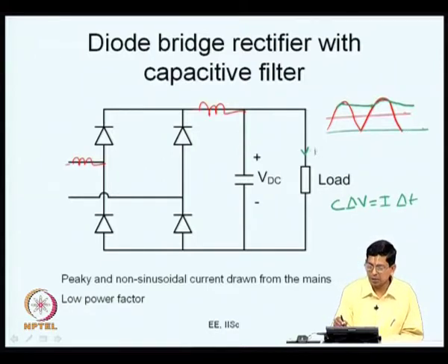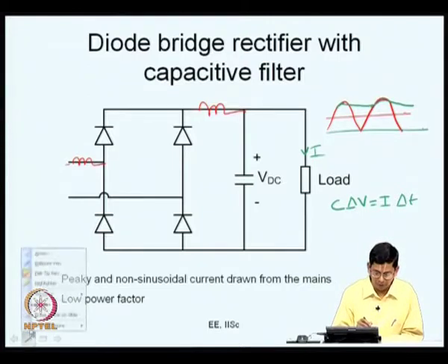During that time the capacitor is getting discharged by the load current I that it needs to flow, and let us say this delta V is the acceptable ripple voltage. So, you need a big enough capacitance to keep the voltage ripple small enough. So, that is what we are trying to look at. This is how you basically choose a capacitance, as you all would know very well.